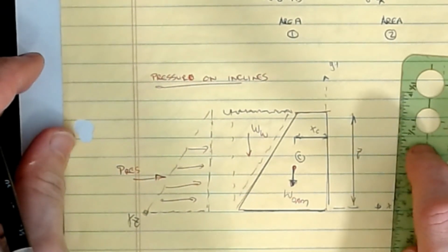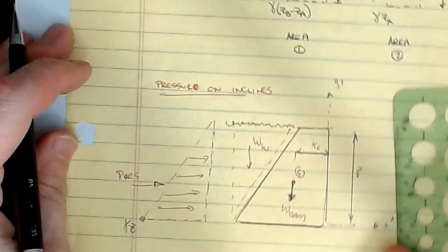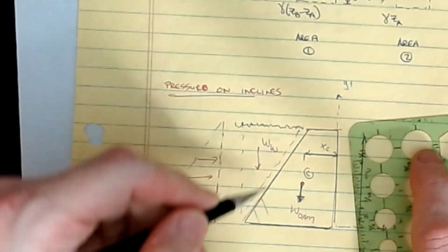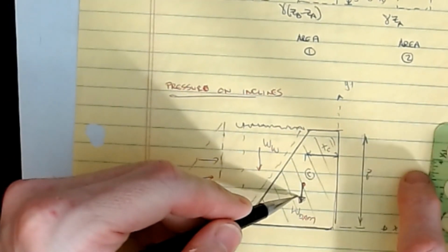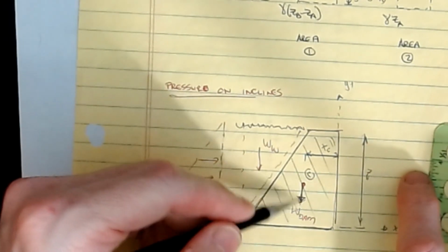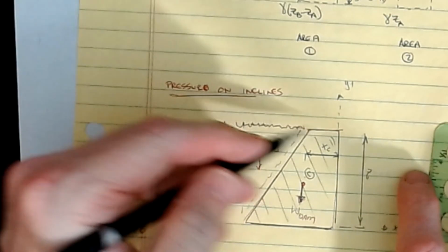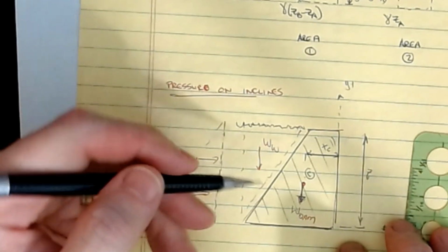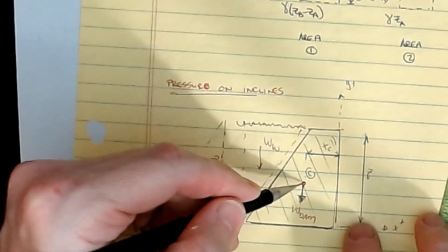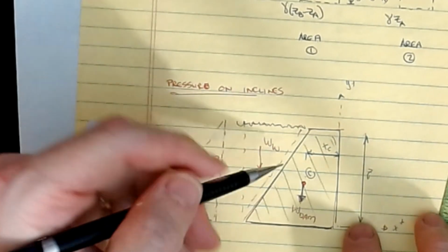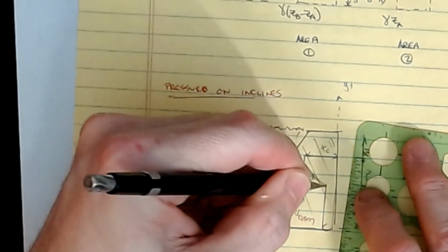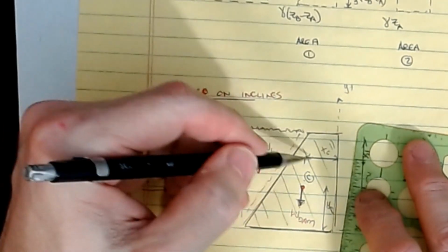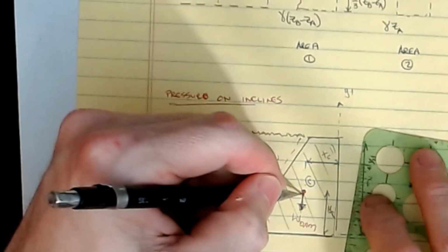That part doesn't change. What does change is the nature of this wall. I'm looking at a solid wall, so I'm going to shade it as a solid value. This dam has a weight associated with it, located at the centroid of this mass, assuming everything is distributed evenly, all those assumptions we made back on day one with centroids. This is on a per foot basis. So I can call this Y sub C, and X sub C would be the distance off of my reference that locates that point C.